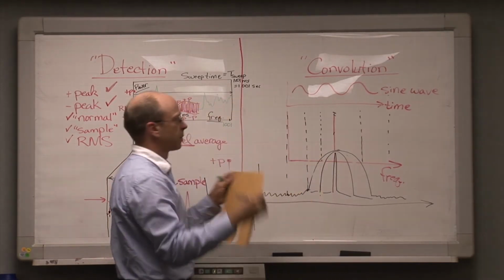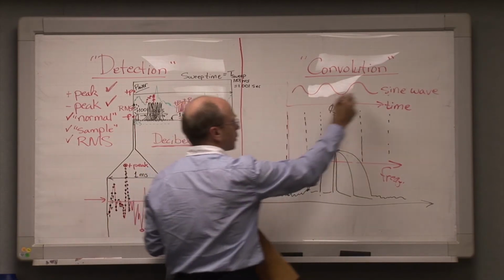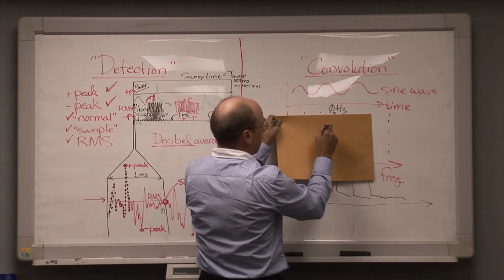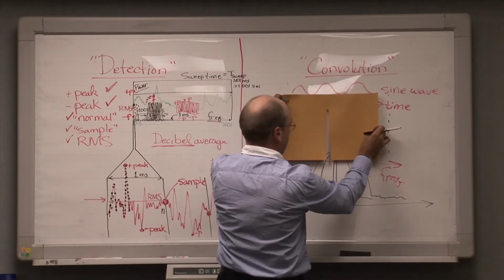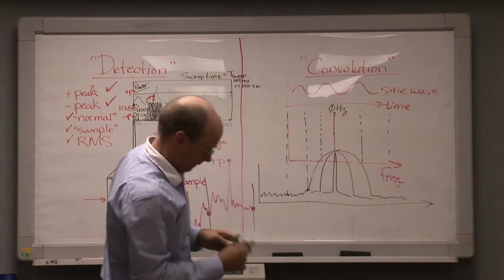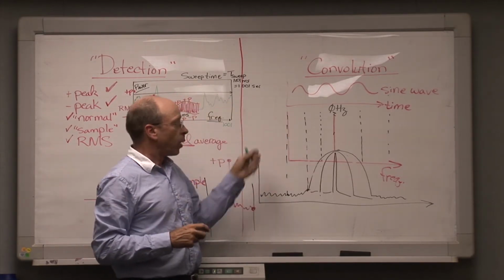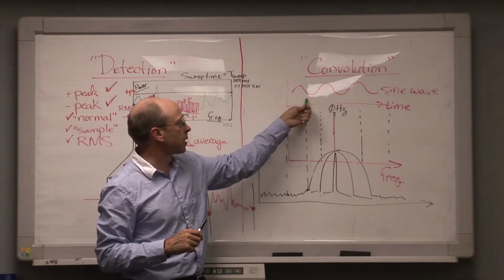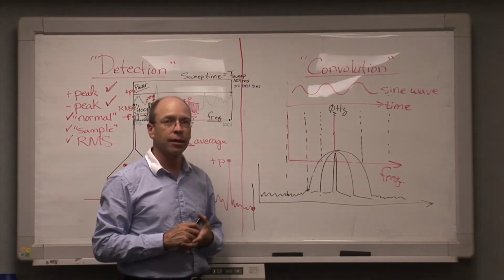Now, can we ever make a measurement that'll show this signal for what it is, being 0 hertz wide? We'll assume it's a pure sine wave. And the answer is no, because to do so we would have to use a 0 width slit, which would allow 0 power through and would take an infinitely long amount of time to step across the spectrum. Well, these are the fundamentals for the spectrum analyzer as seen on a whiteboard. Now we'll transition to the lab portion where we'll actually look at some signals like this with a spectrum analyzer, and we'll look at the various functionalities that I've just described.